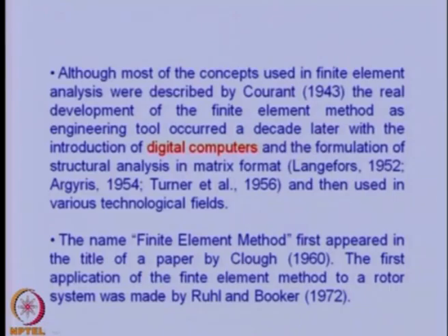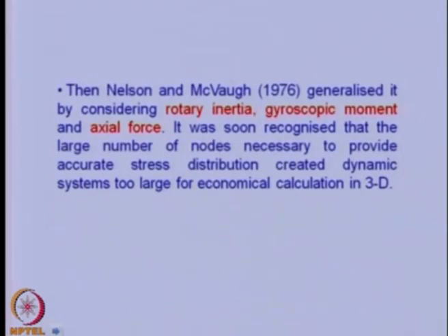The first application of the finite element method to the rotor was made by Roux and Booker in 1972. Then Nelson and McVaugh in 1976 generalized it by considering rotary inertia, gyroscopic moment and axial force. It was soon recognized that the large number of nodes necessary to provide accurate stress distribution created a dynamic system too large for economical calculation in a three-dimensional solid model of such rotors.